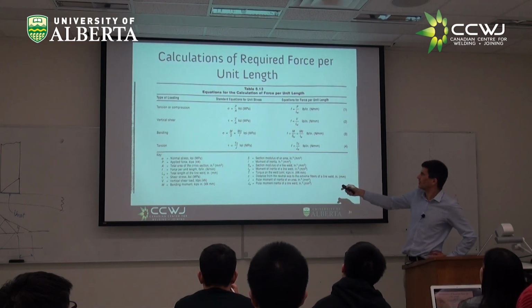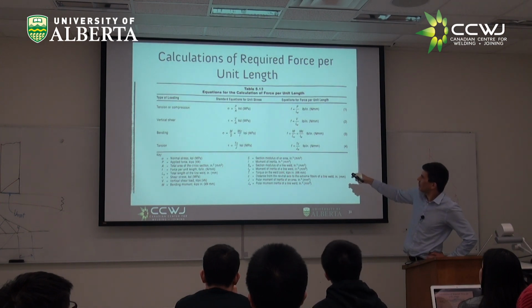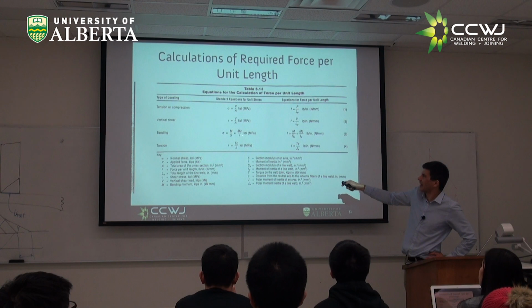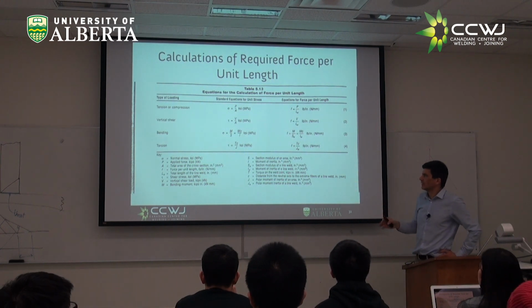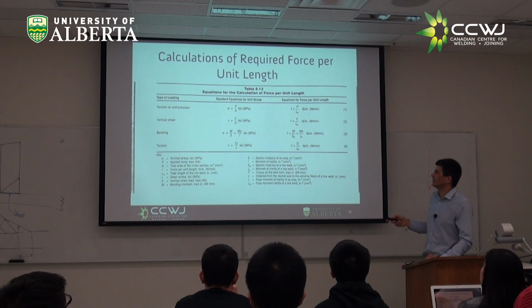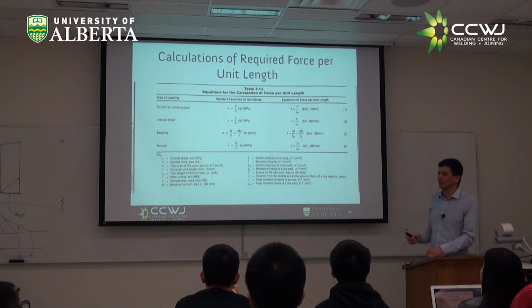It's just a formula, and I'll tell you how to plug things in. And the funny thing, you knew this. This is the equivalent for welding: moment over the section modulus of the weld as a line. And the same for torsion. This J is the polar moment of inertia, and this I is the moment of inertia around one of the axes, the transverse axis. Same thing.